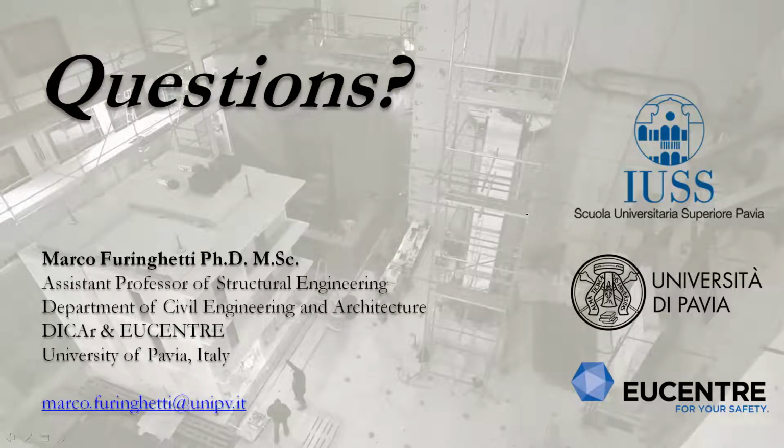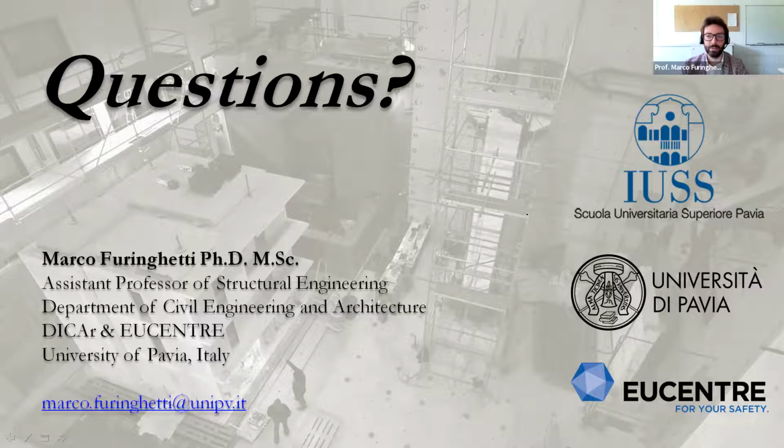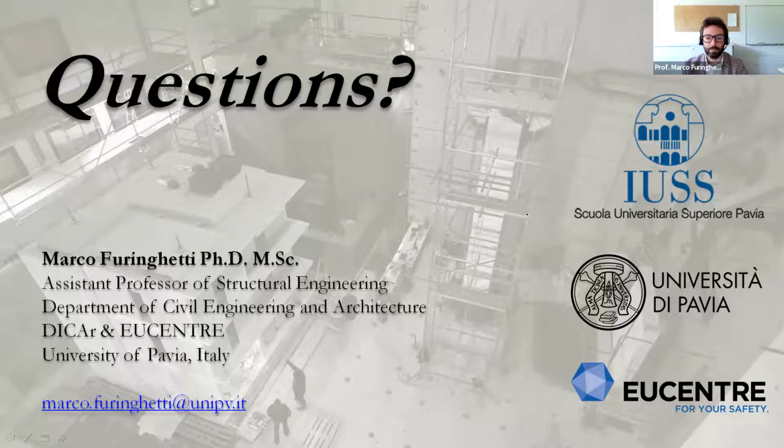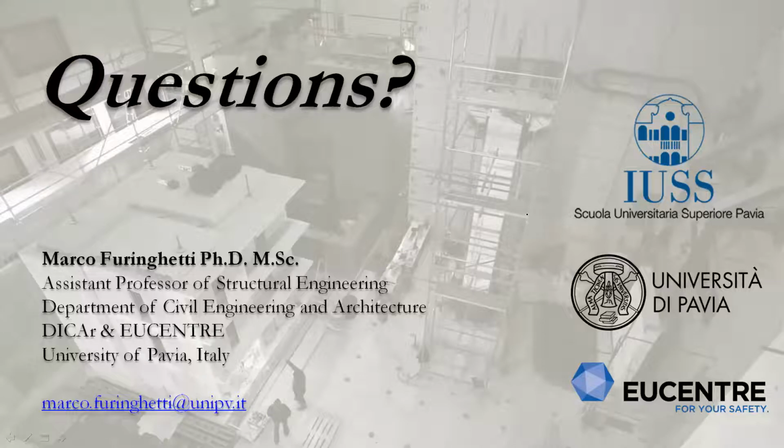Yes. The first one is related to the damping, and which formulation, which model of damping should we use? Is it better to use the Rayleigh damping, mass damping? Can you say more about the damping? And if, for instance, we were going to use the Rayleigh damping, which periods of interest should we assume as boundaries, let's say, the two fundamental periods? This is the first question.